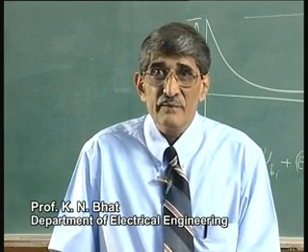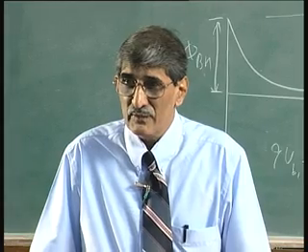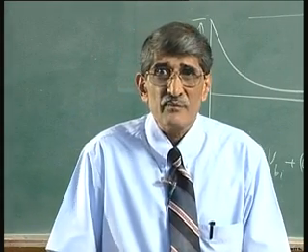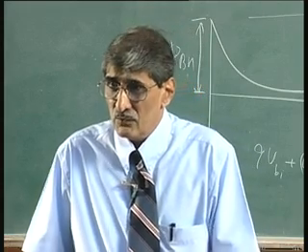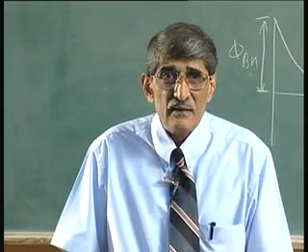If I take a semiconductor with a larger band gap, you will get an even larger forward voltage drop. So, with metal semiconductor contact itself, we can get performance quite close to, and as good as, a p-n junction. With that, I will close for today. We will continue this discussion, some aspects of this and the non-idealities etc., in the next lecture.